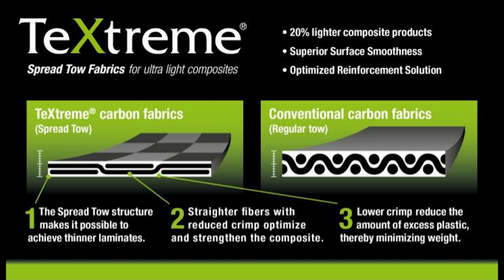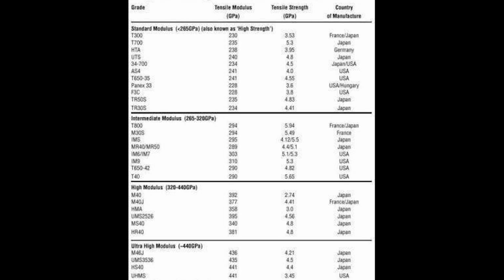Yeah, I can actually explain what it means. They definitely used a heavier tow, but they didn't spread it. So it's not spread tow, it's just woven tows. It's like 12K, so it's just bigger. I believe it can be a 12K that is just woven, which means it's a much thicker fabric than the one we are using. I would guess it's at least 200 GSM, maybe more. But it doesn't say much about what type of fiber it is.